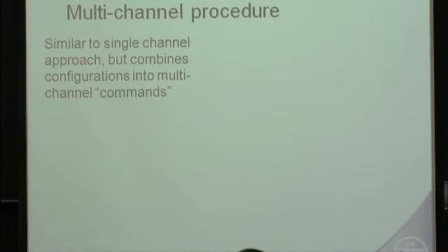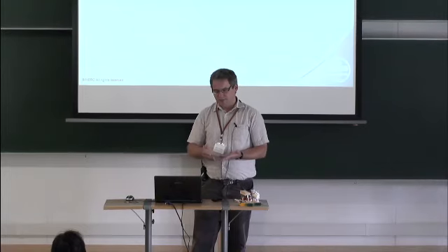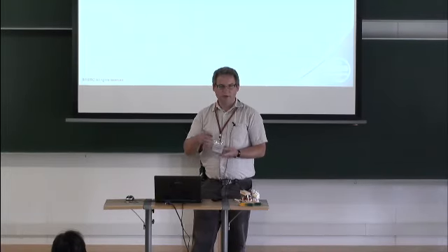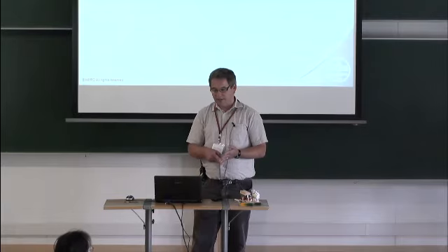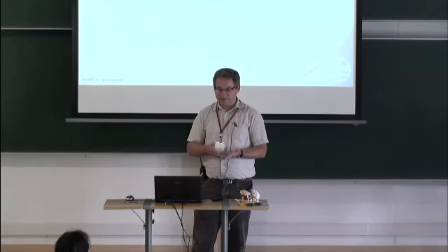Now what we haven't done up till now is really taken advantage of how the resistivity meter works. At the moment the procedure has been working in what we call single channel operation. That's measuring one potential difference for one application of current. But that's not very efficient. The resistivity meters are multi-channel instruments. They can make multiple potential measurements for every current pair.